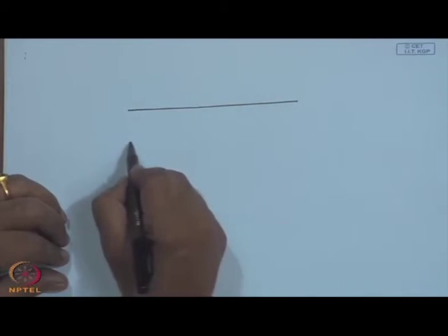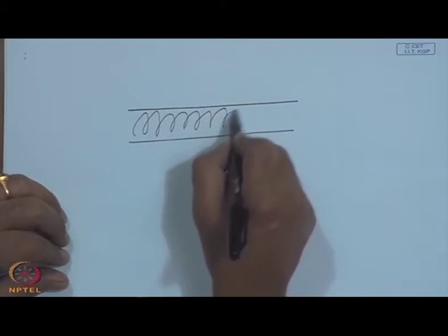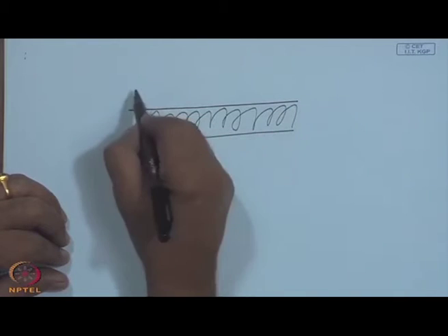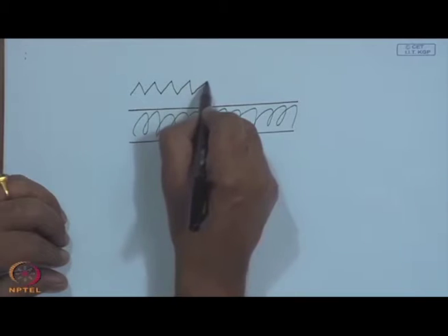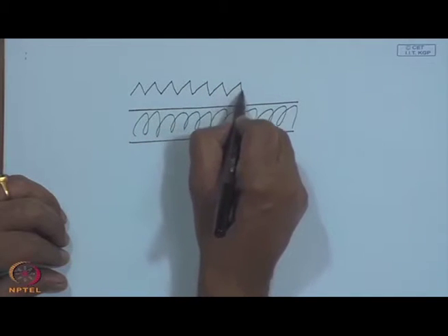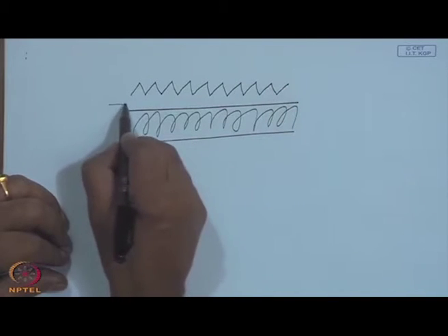Then once again the whole game has been to improve the heat transfer coefficient, improve of course the absorptivity. So, people came out with, instead of these fins, one can have a corrugated sheet absorber, and the flow is in this direction.